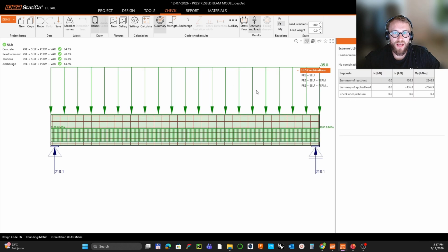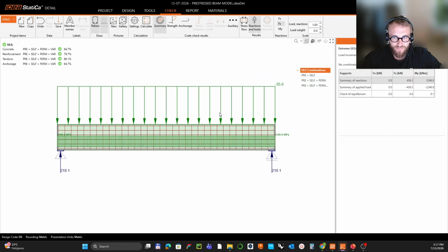So at first, I encourage you to always double check what is happening with your external and internal forces as reactions. It has to match: external loads have to be equal to internal loads, or mostly right now in this form the reactions, to have static equilibrium.